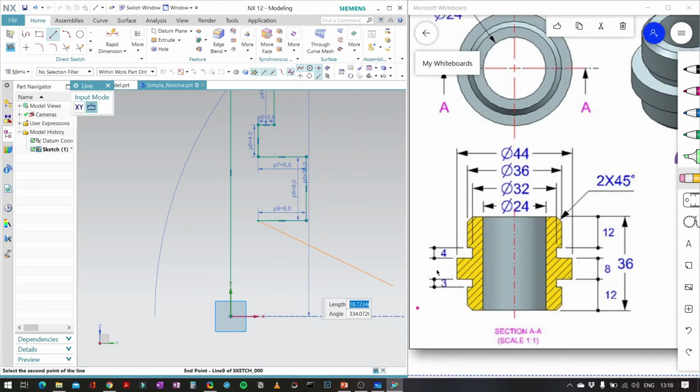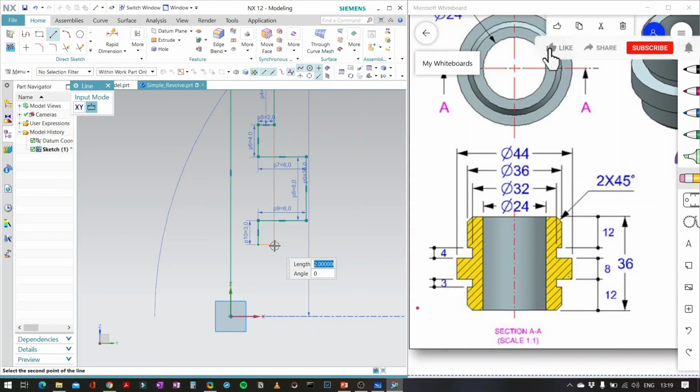How deep it is? It is 3 mm, so we'll go as deep as 3 mm by 3 mm. Now again, what is the difference? Again it is the same. So how we can do it is, we can directly enter the value as 2, or you can simply go here on the right hand side. It takes reference that you have to align this particular end of the curve with the vertical line which is already above, and you can see this dotted line which is auto generated, that is only for reference. We can simply click OK.